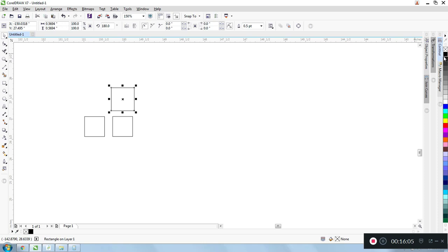And yeah, so in most laser software, regardless of whether it's RDWorks or the ULS interface or Trotec, you have different operations that you're going to want to do with different colored lines. I may want my black lines to cut all the way through, and I may want my red lines to just score a mark, or I may want things to happen in a particular order.